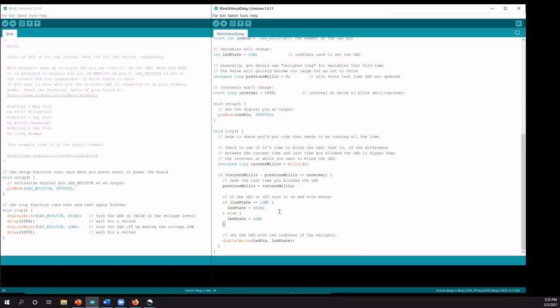And every time the if statement reads true, instead of turning a light on and off, you're going to read your sensor. As long as the stuff inside this loop can be executed fast enough, now you have a sensor being read at evenly paced, predefined time intervals, like a regular sampling rate. And that's how you can use a cheap microcontroller to do real data acquisition.